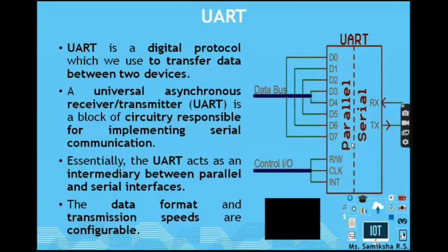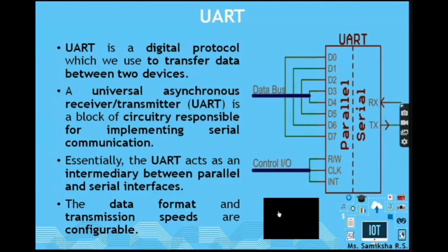You can also configure the transmission speed, that means the speed at which the data bits will be transmitted. You can always configure that. So all these different features are provided in UART. It was clear that how we adjust the transmission speed depends on the baud rate. Baud rate.